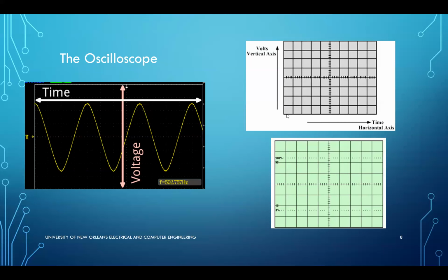If I have set up the x-axis, or the time axis, as 1 second per division, then I will be able to see 10 seconds of the signal at a time. If I want to see more of the signal, then I can make these squares worth less. And if I want to zoom in, for example, I can increase how much I'm dedicating to each of the squares. In any case, that's the same information you see here, right?